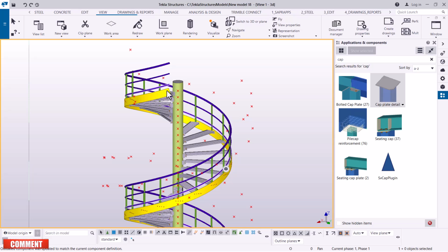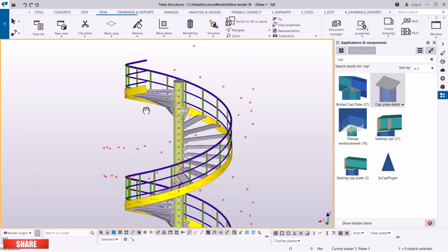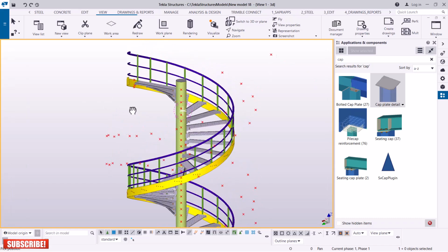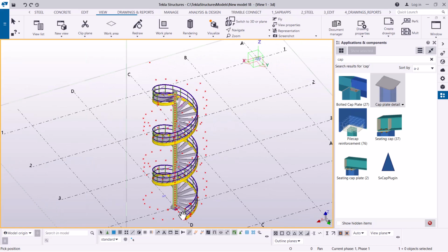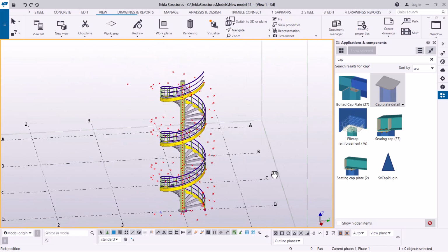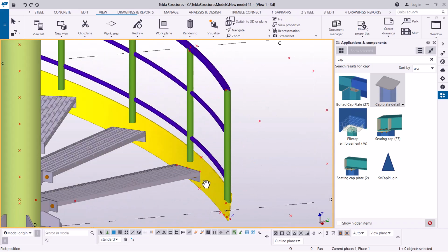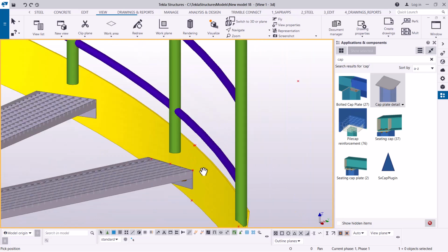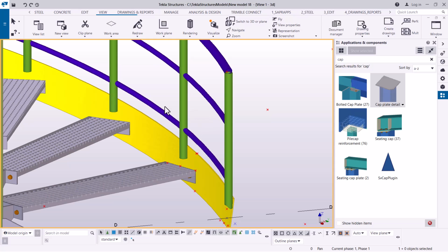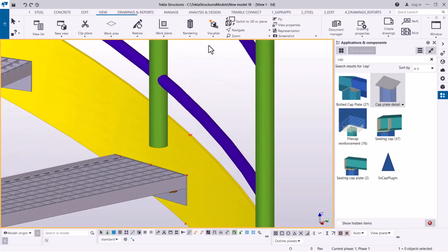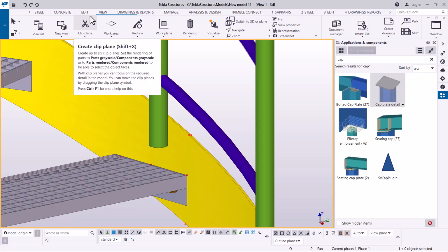But don't worry about the exit, where the staircase exits to. The main purpose is just to show you the tips and tricks on how you can create a spiral staircase in Helical structures with the simplest tools available in Helical structures. Now the part remaining here also, let me just add some details here. I want to trim off this. Remember, I changed the post to circular hollow sections because it's less harm for the users of the staircase, because the angle profile has some sharp edges, which could expose the users to some sort of danger.